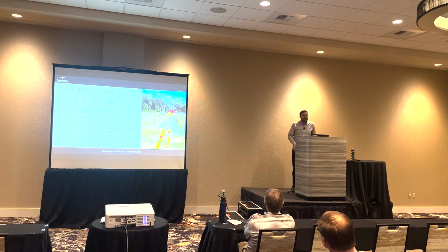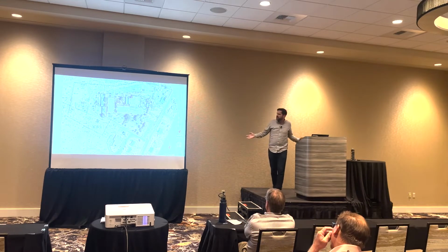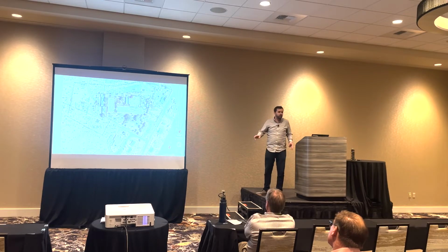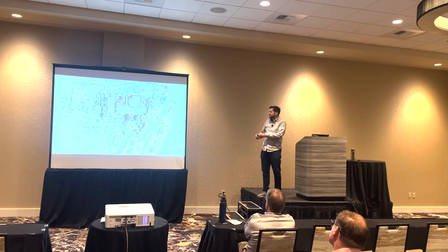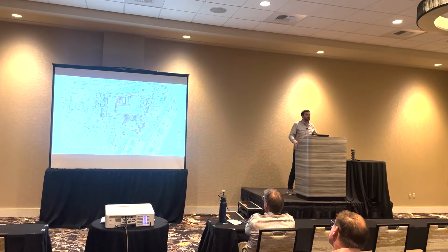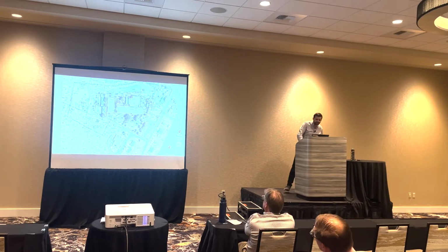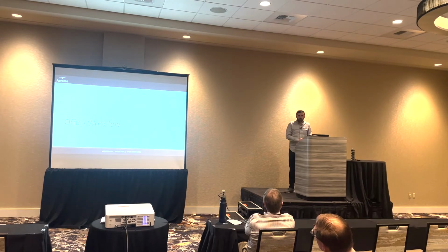Because at the end of the day, what your clients want almost always is just going to be this: a finished survey. It is a sealed survey. And it doesn't even necessarily say what was taken with a GPS, what was pulled from records, what was taken with drone photogrammetry, what was taken with Lidar. This project, I know, is a blend of all of those things, and you take the right data and put it together to create the best survey in the best way possible. That's what your job is, and that's what our job is: to help you figure out where Lidar makes sense, how to get that data in a useful, practical way, and then how to get on with your lives as well. All right. So, those are the basic principles.